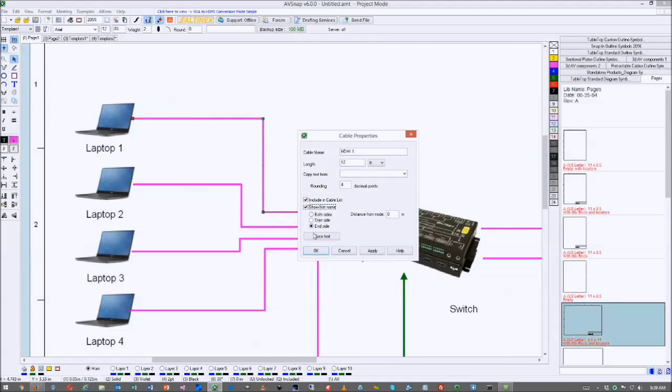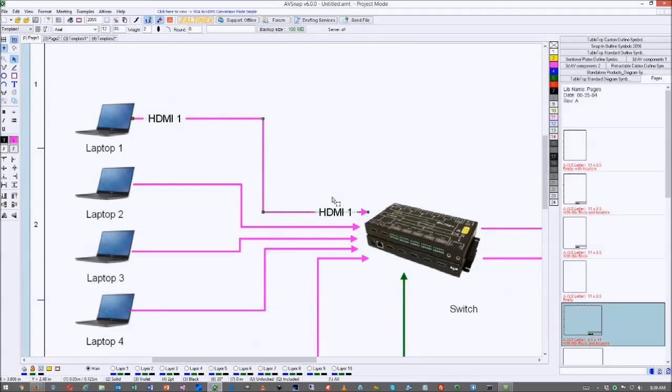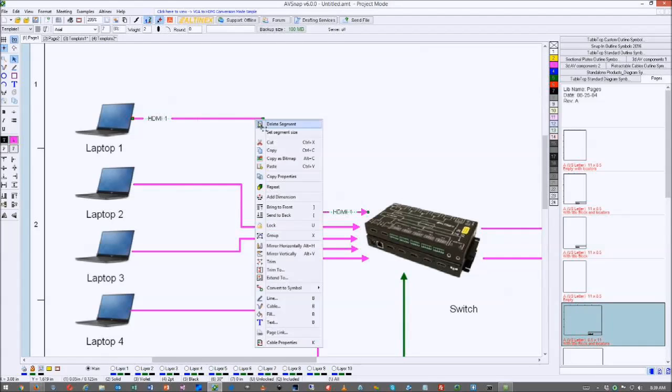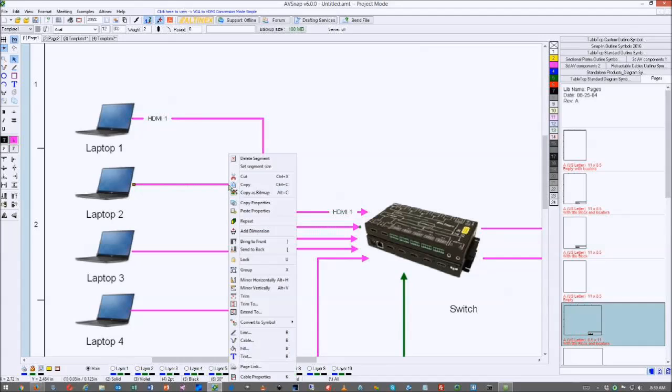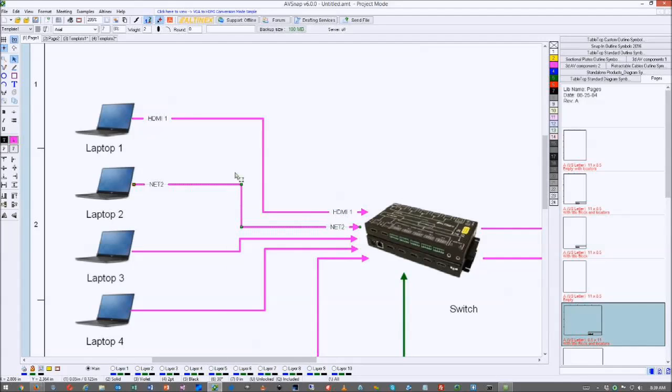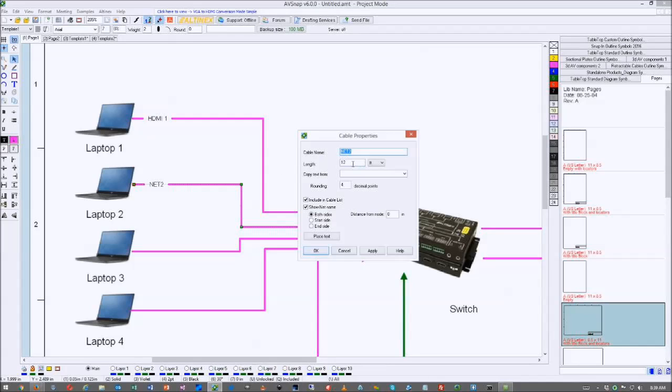And I want to show the net name on both sides. And as you can see, the name of the cable appears on both sides. I can use the weight and the size, and I can just come down here and make it a little bit smaller so it's not as pronounced, okay? And let me see if we can do something else here. Copy properties and paste properties. You can see that I can make it so it appears on all of them. You'll still have to rename this net. So pressing here, we'll put K and put HDMI 2.